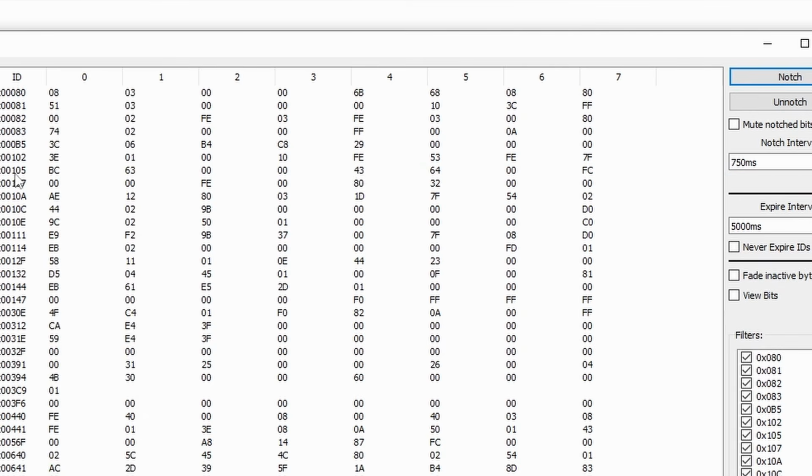So that's a clue. That is CAN ID 105, 0x105, byte number 4. And so that's how you read this. Across the top column, there are 8 bytes in any CAN ID. So we can see they're labeled. Number 4 is here. Attribute 105, CAN ID 105, byte number 4. So that's our first clue, brake switch.